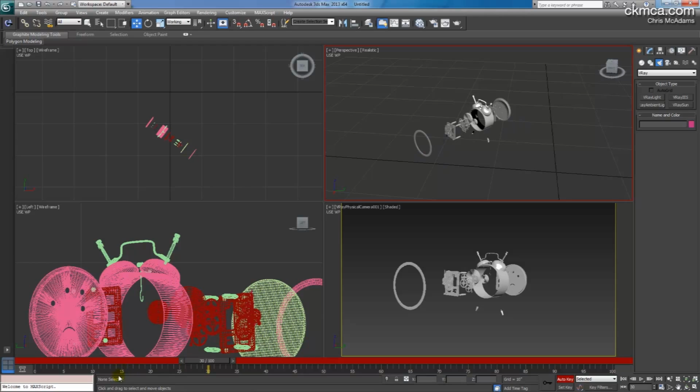You could imagine if I didn't set a key by clicking the key at 15, then it would create motion between 0 and 30 for the glass and the bezel. I don't want that to do that. I want that to happen from 15 to 30. And actually I'm going to just jump all the way out to 60, and I'm going to try to combine everything and have it all collapse between frames 15 and 60.